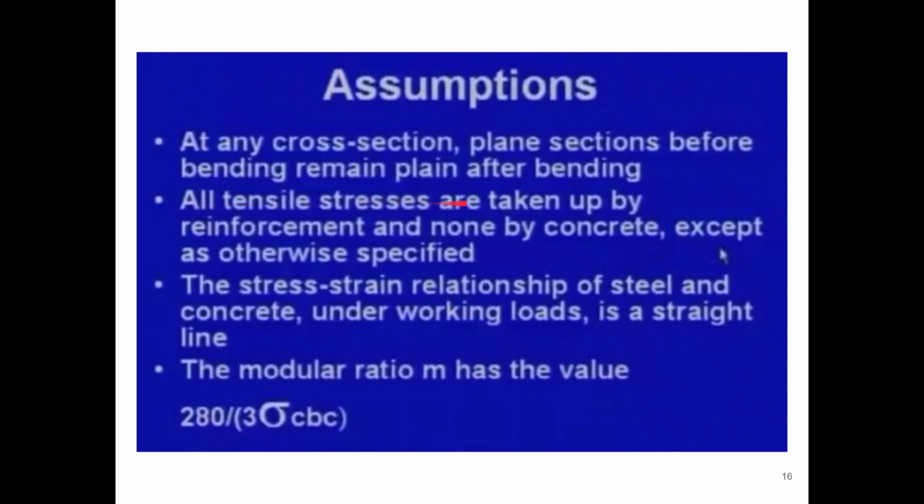Apart from that, all tensile stresses are taken up by reinforcement and none by concrete, except as otherwise specified. So I mentioned this point just now. The below portion, that is the tensile portion, is always taken by the reinforcement. So we are taking a very good factor of safety, and we assume not by concrete. And the upper portion, which is the compressive part, is taken by the concrete. So basically we underestimate the capacity and overestimate the loading conditions.